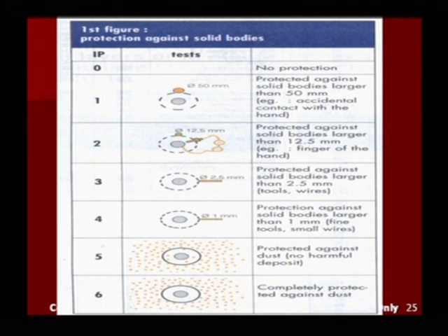Okay, so up to this point we've talked primarily about the American classification for enclosures. NEMA 1, NEMA 3, NEMA 3R, NEMA 3S, NEMA 4, NEMA 4X, NEMA 7, 9, and 12. In IEC terminology, they actually have an IP number, and it's two digits, so IP56, for example.